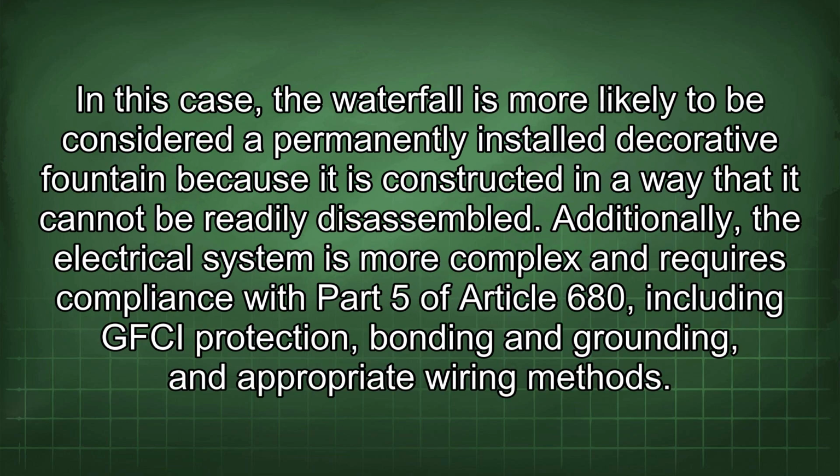In this case, the waterfall is more likely to be considered a permanently installed decorative fountain because it is constructed in a way that it cannot be readily disassembled. Additionally, the electrical system is more complex and requires compliance with Part 5 of Article 680, including GFCI protection, bonding and grounding, and appropriate wiring methods.